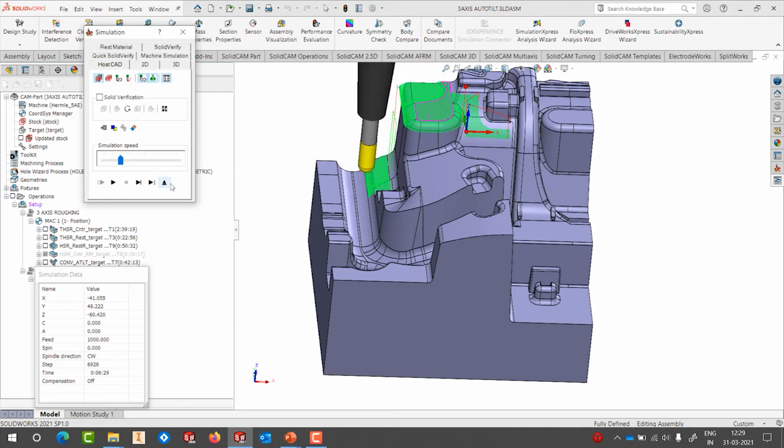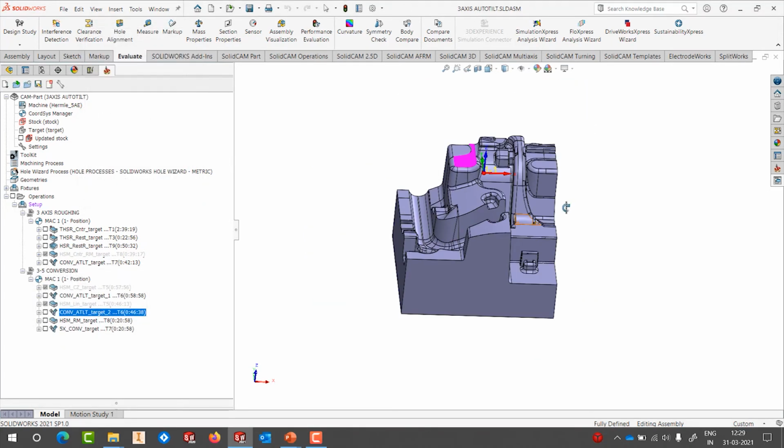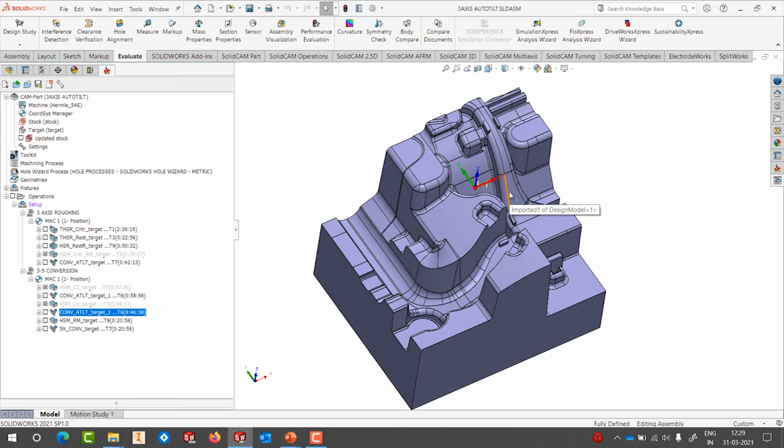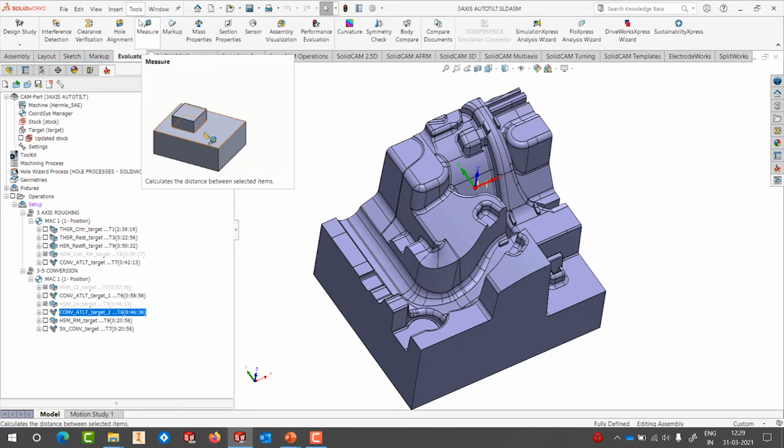So you can actually take any of the toolpaths like HSM or turbo HSM and convert them to 5-axis simply by providing it the tool with a holder. So you can actually use short tools to machine deep jobs if you have a 5-axis machine, and convert a simple looking 3-axis toolpath to a simultaneous 5-axis toolpath, and that is done by avoiding collisions with the holder. Right, so that was about generic 5-axis.